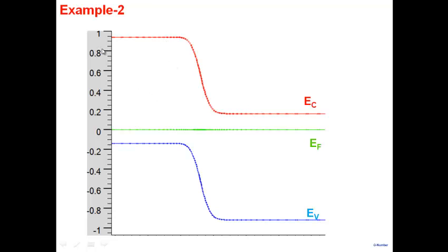And note, the diagram has an energy scale attached to it. So I know what the EC value is here. Whatever the EC value is, I can read it. And therefore, from this diagram, by taking a difference here and a difference here, I know how much the potential is inside my semiconductor here. What kind of a potential will it be?